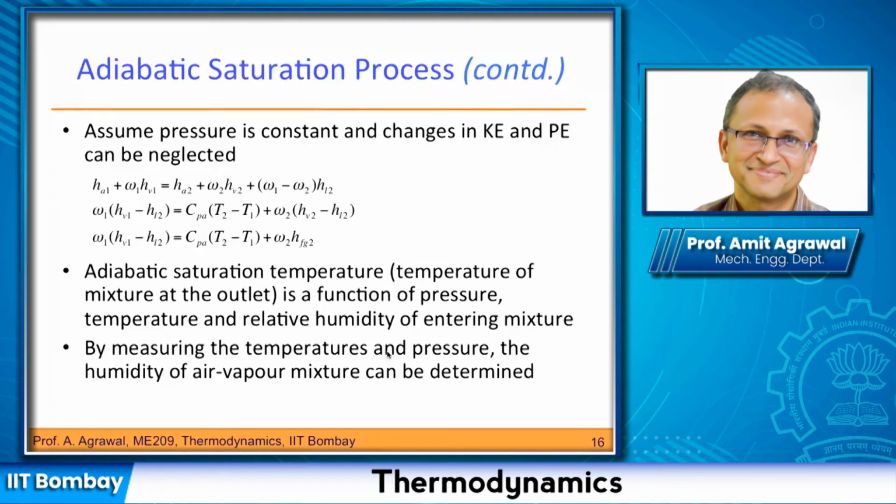That means it is not exchanging any heat with the surroundings, which is a reasonable assumption in this case. This expansion of the gases leads to cooling, and that leads to an increase in the saturation level. At some point, the saturation level will become 1, and that's where the cloud starts forming. This is just one example of an adiabatic saturation process.